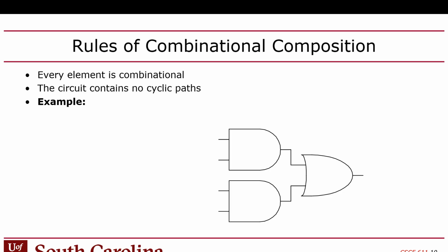Okay. So in combinational logic, you have to make sure that every element inside your combinational logic circuit is combinational. So in this lab, in lab 2, these 7-segment decoders are purely combinational. There's no memory. So we're going to connect the inputs of these modules directly to the switches on the FPGA board, and then the outputs will go straight to the hex decoders, which are also connected directly to the FPGA. So we're going to connect these things between the input pins and the output pins in the FPGA, which will bridge together the switches and the hex displays. That's the goal. And there's no memory involved there.